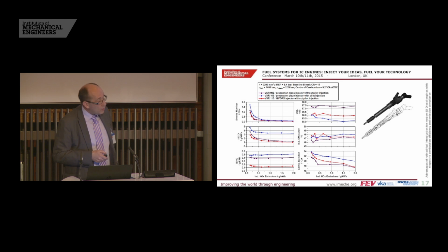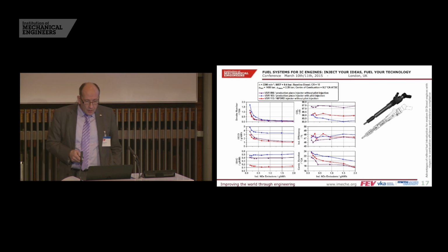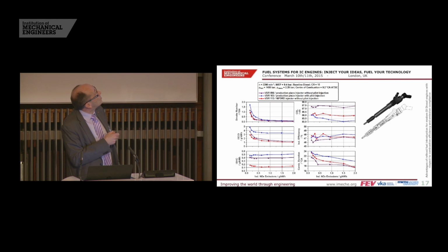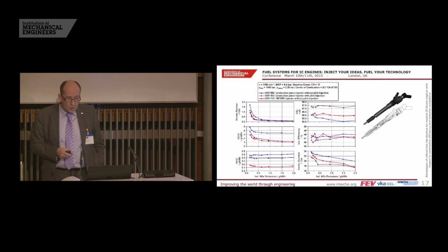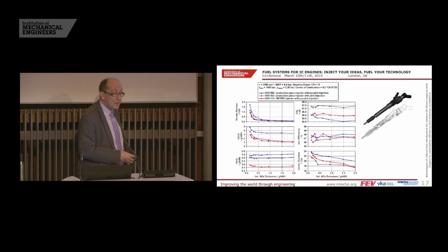The first example, we have here an EGR sweep performed at the mentioned load point, 2280 RPM and approximately 8 bar IMEP. We have selected certain settings, and you see that in this variation, the high force injector is compared versus the standard piezo injector, once operated without and once operated with a pilot injection. And you see here, if you go through the results, starting with the emissions on the left side, we can more or less duplicate the emission performance of the piezo injector without pilot injection, so very good in terms of NOx-smoke trade-off.